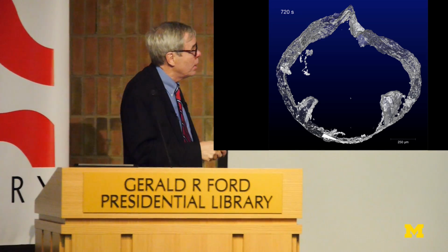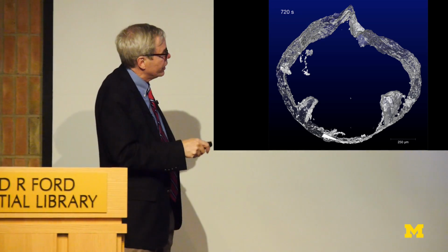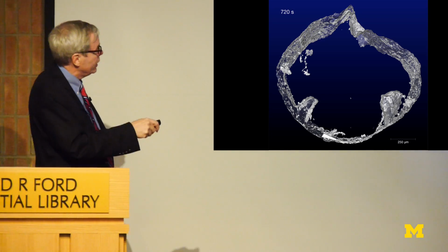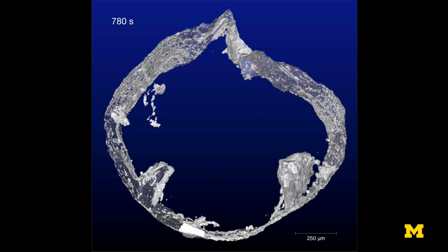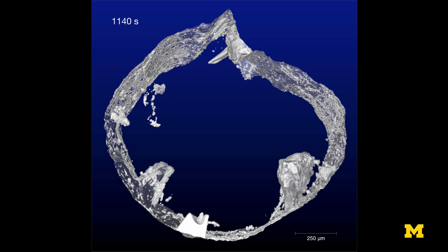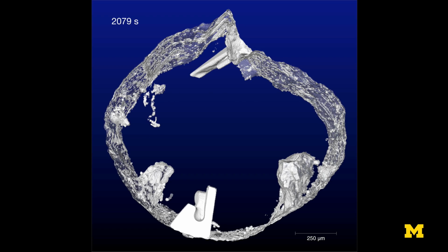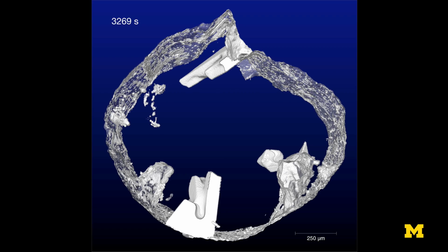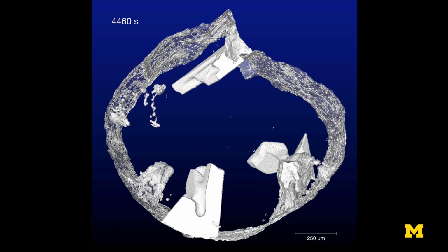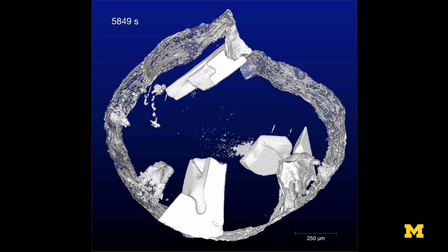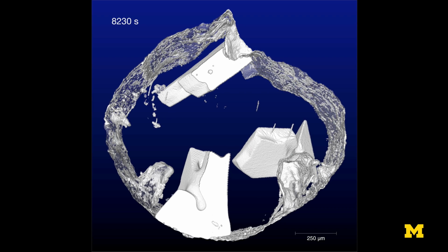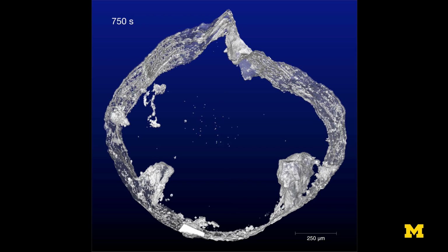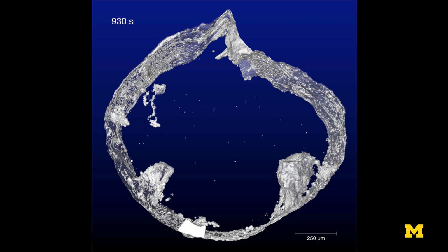So this is aluminum, copper, silicon liquid. This is the crucible here. There's a time counter here to give you an idea of the time scale. And the primary silicon phase nucleates at the edges of the crucible and grows into the liquid. And you can see it grows in. They have a truly faceted, very plate-like structure here. If you look down here, it doesn't look so faceted, right? So the question is, why is that true? And I'll talk about that in a second.